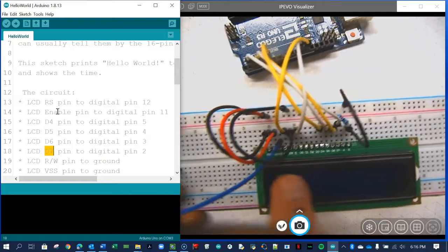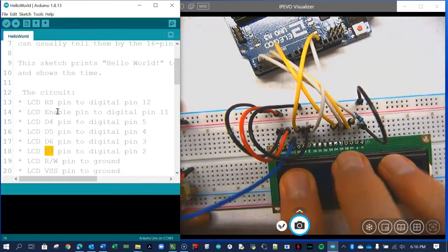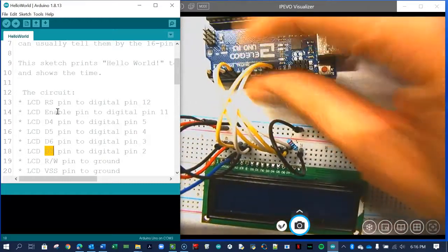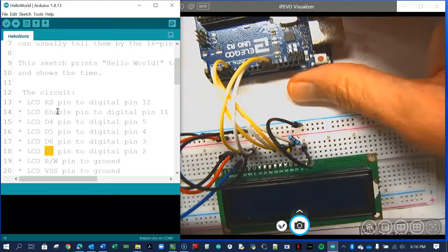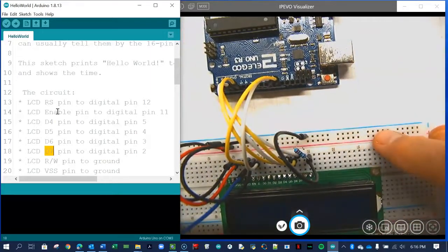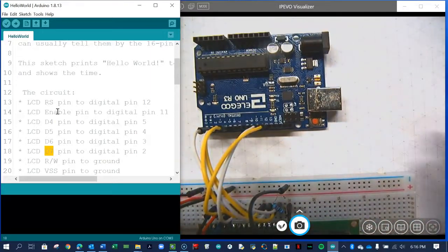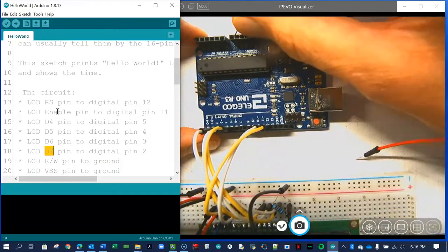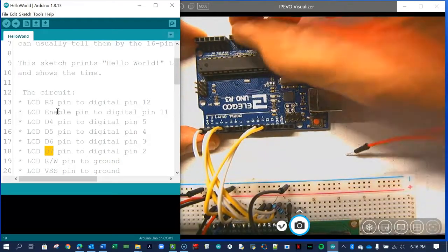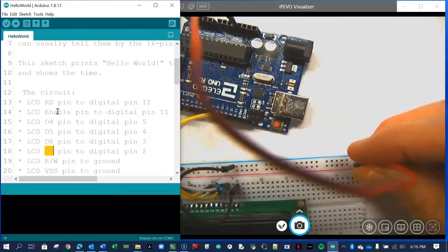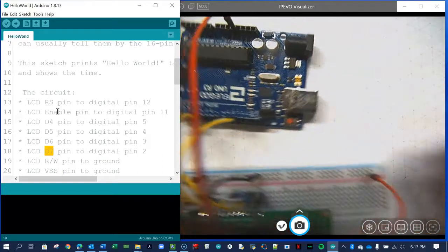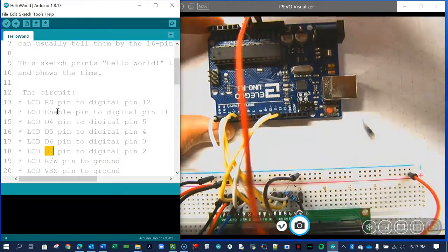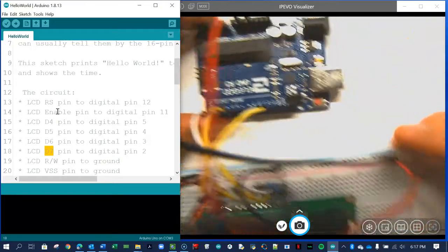There's 1 wire in each column, and that's it. They don't have multiple wires in a column. So double check that. Double check everything's connected. Lastly, of course, we need to heat up our rails here by connecting a red wire to power. So this is going to be 5-volt power. That's VN, ground, 5 volts. Again, make sure that your power goes into the right bus. And then my ground wire, any of these are ground over here, goes to the ground.